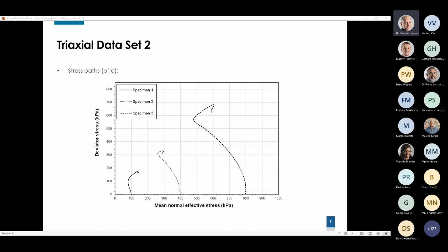And I think she was successful, if I remember correctly, in being able to continue to measure reliably what happens in the shear plane and where everything then happens once that plane develops, and to show that the stress path would continue along the critical state line, would not hook back like this. Knife against my throat, I cannot think of a practical, real reason why a stress path would divert in that way. To my mind, that tail end there is an artifact of the experiment and should be discarded in the interpretation.